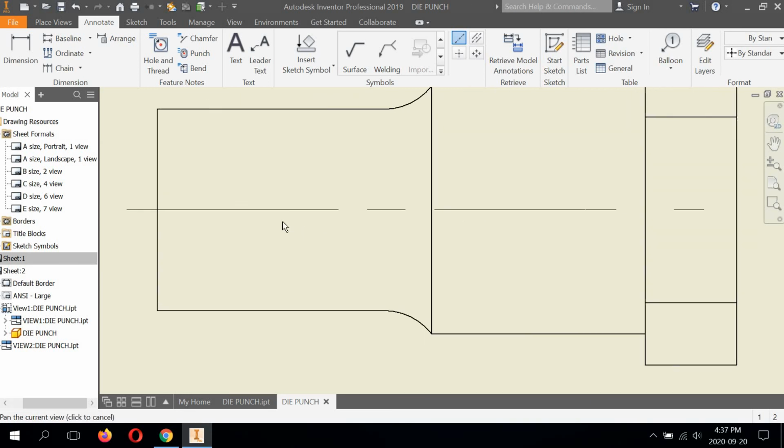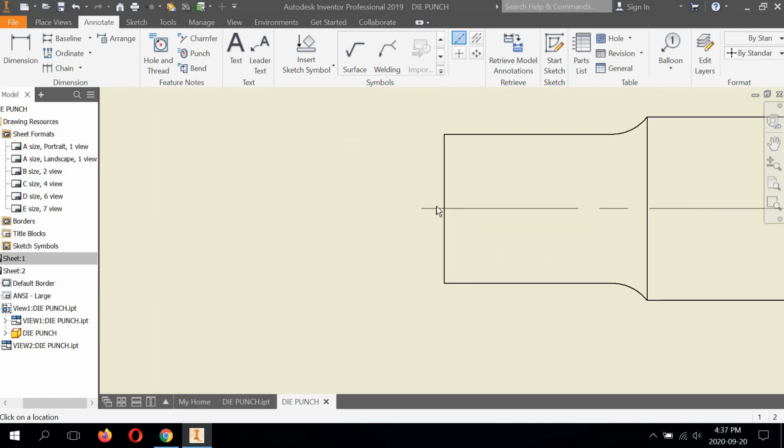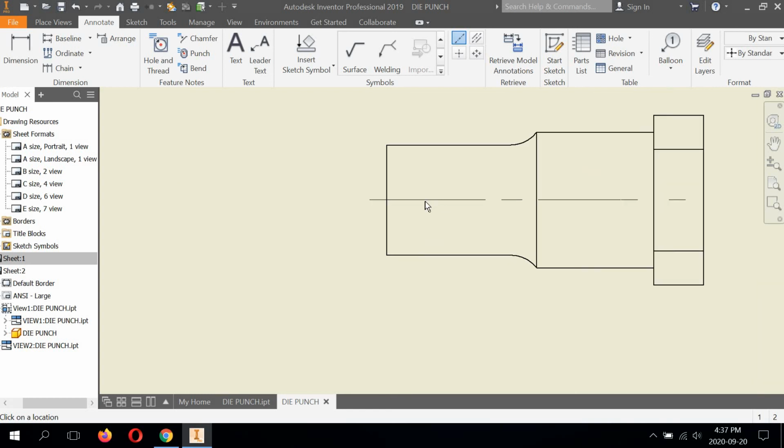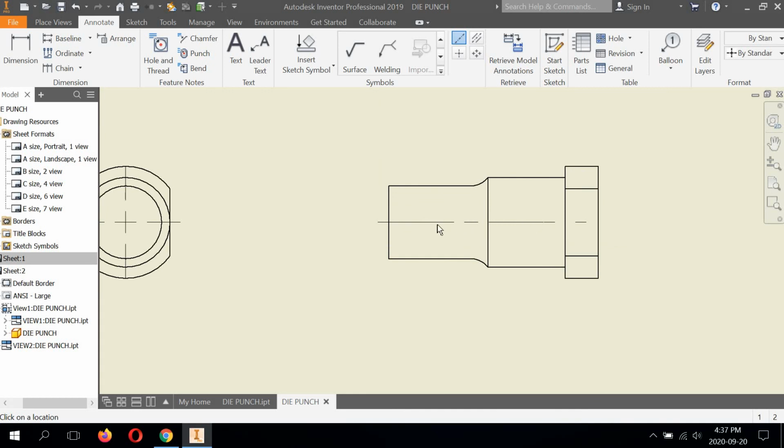Now you're going to notice the center line will automatically give you an intermittent dash every so often, and it always extends a bit beyond the feature it's describing. Now this is so it doesn't get confused with physical geometry that needs to be constructed or manufactured in a shop. And the center line appears lighter than the line work in the physical part that's being made, right? We don't want to confuse these lines with something to be made in the shop. It's just, again, a drawing standard that has to be added to a mechanical drawing.